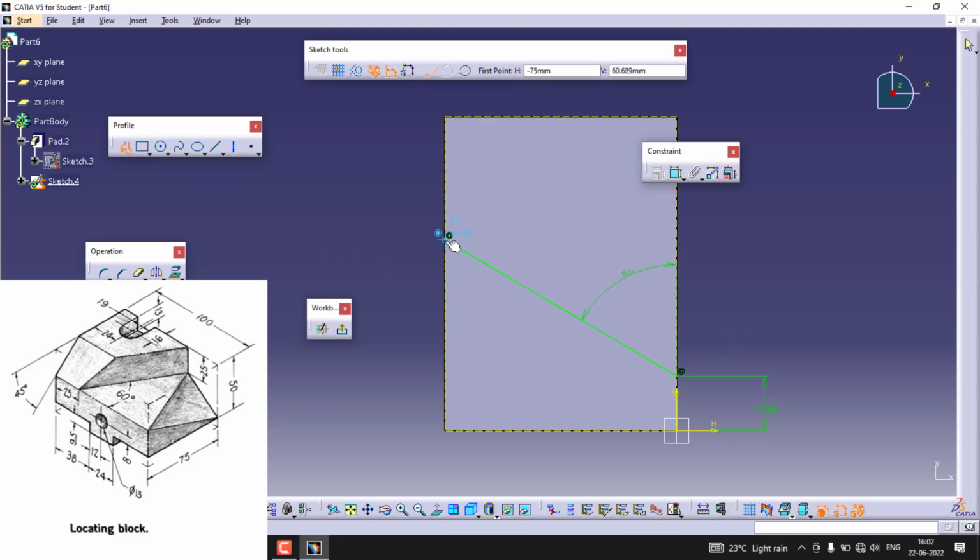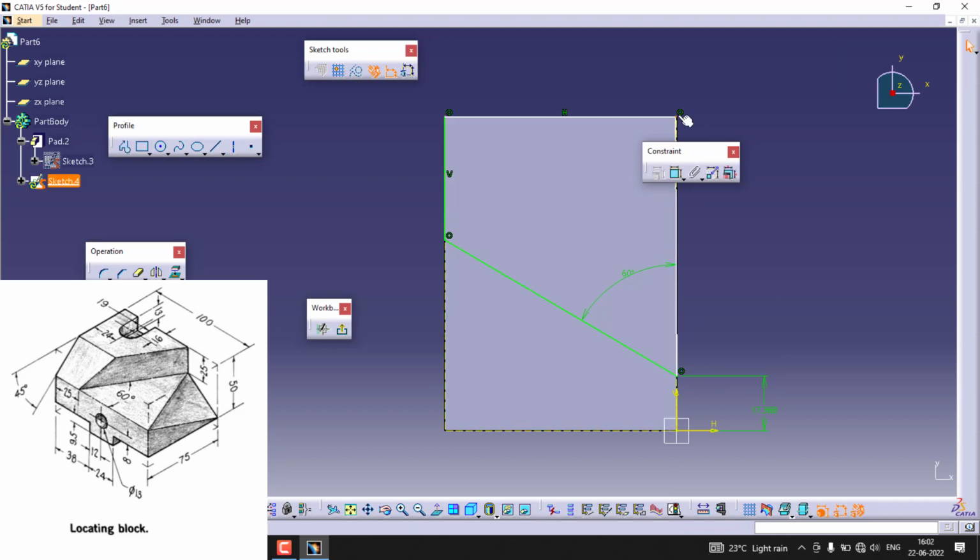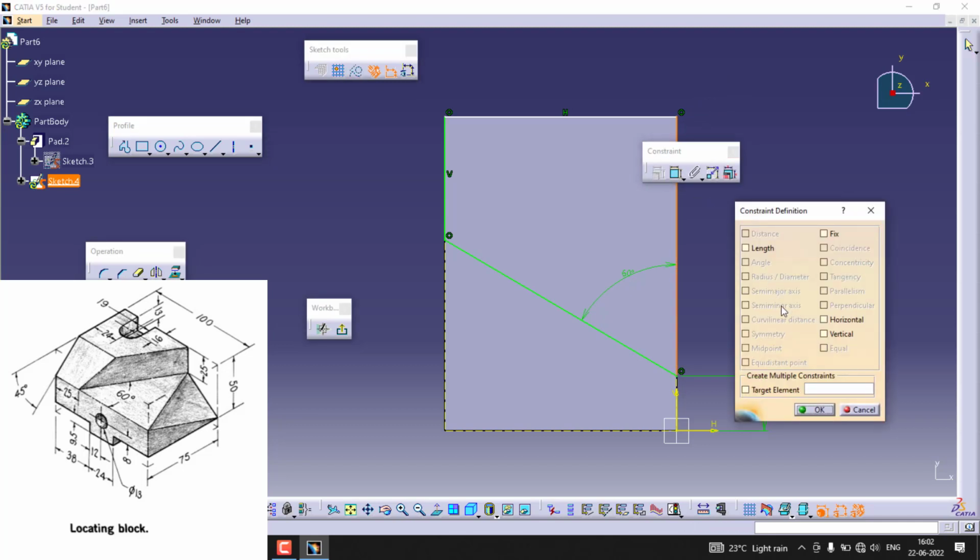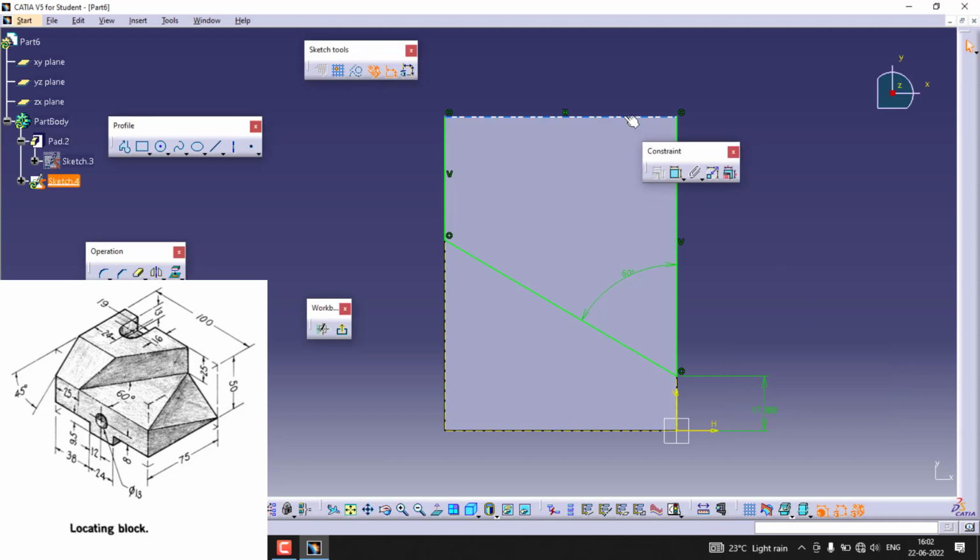You can close the sketch that side. Sometimes you won't get the reference. You can use the geometric constraints for that issues. Okay, this is done. So this point should be actually, if you refer whole face into account as a reference now, it will create this issue. So better just select single entities and refer them as a reference. It will help you to just snap the same face edges into account. I had faced this issue multiple times, just repeating the same.